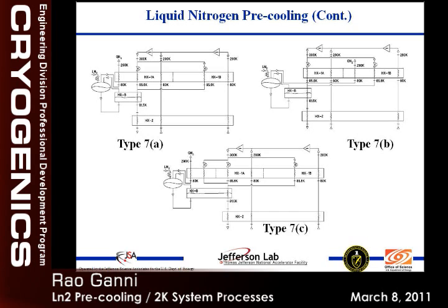Then you may need to balance the high side flow against these, and you may use different arrangements where you can shift it. Most of the refrigerators, if you see in the field, have this medium pressure coming back very cold, wasting the refrigeration because of the stacking arrangement and they are not exchanging heat properly, or if you change the mode, it gets worse. So they all need to be thought through in the design phase, so you are making provisions in case this is what you anticipate.